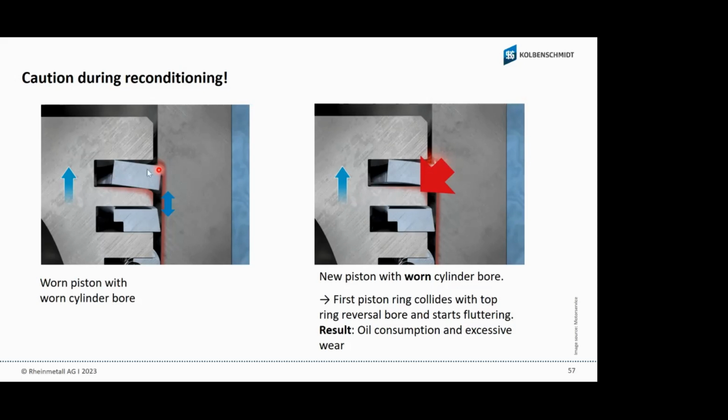I said, yes, this is right, exactly. This was your fault. You must open the engine again. You must change or overhaul the cylinder bore to oversize. Yes, this is right. I thought it was not so critical, but now I know it.